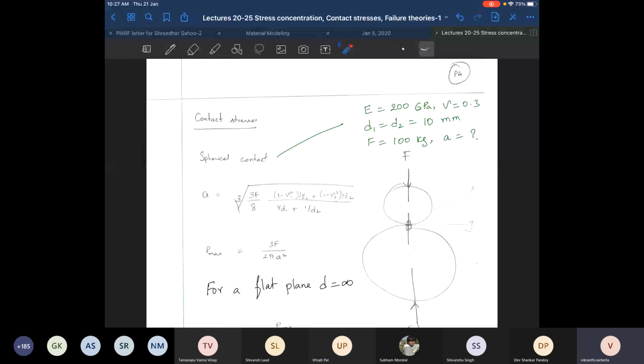So even if you use a taper, let us say you have a taper. So this is one section, this is another section. You are saying let's do something like this, right? Now, what is the radius of curvature here? Taper does not eliminate the radius of curvature. You will always have a fillet because the tool has a certain tool radius. Whatever you do, you will have a fillet. It is just the question of what is the fillet radius.